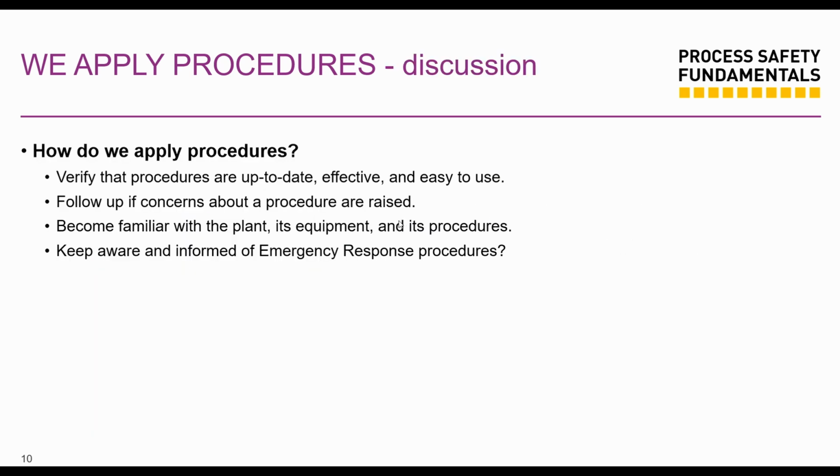So how do we do this? How do we apply procedures? Verify firstly that your procedures are up to date, and they are effective and easy to use. You don't want to combine 10 steps into one line, like "start the pump." You need to explain it, break it down step by step. Follow up if concerns about a procedure are raised. Become familiar with the plant, its equipment, its procedures.